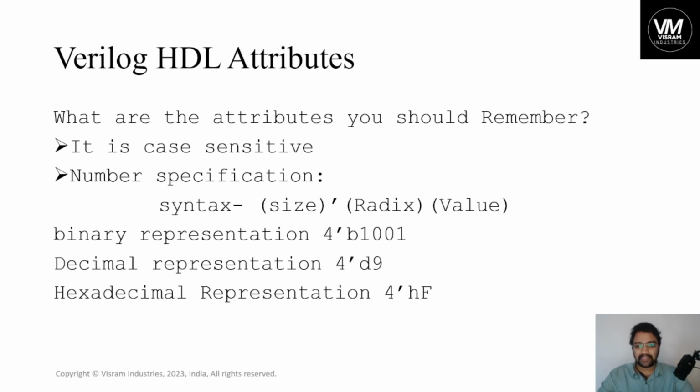First, Verilog HDL is very case sensitive. You should be declaring only in lowercase or only in uppercase. You should use the same terminology at the beginning of the code and at the end of the project as well. If you change the names from one Verilog HDL file to another on the same module, it will be difficult to debug at the error stage, or difficult for the machine to understand whether all the modules are interconnected or not. So it will be chaos again.